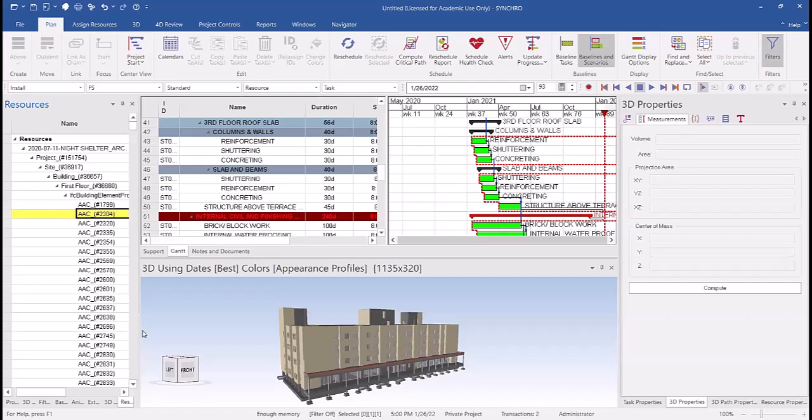Integrating VR with the Synchro system can be done in different ways. You can export data from Synchro in the file format of FBX or OBJ. You can choose a VR platform such as Unity or Unreal Engine, which supports VR integration. You can import the exported 3D models into your chosen VR platform. You can set up the VR environment, like configure the scene. You can add interactivity, there are various ways of doing it. So you can test on VR software also.